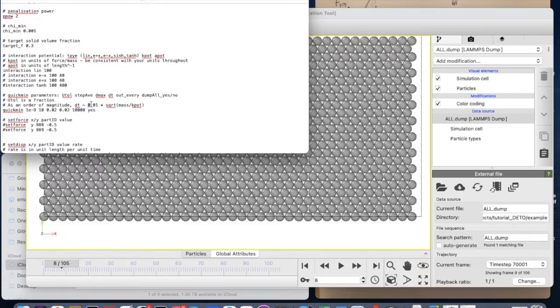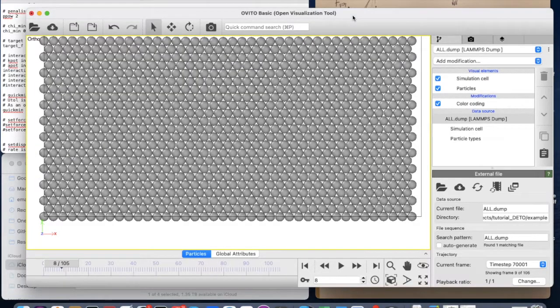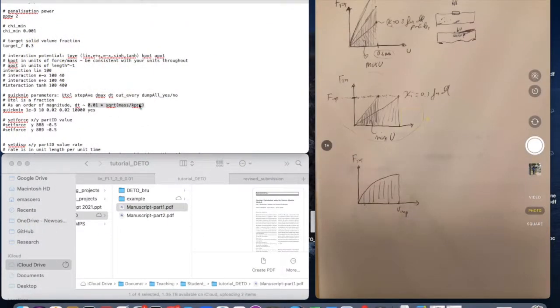It's just an indicative quantity. My suggestion is you take this as an initial guess, and you see whether the system is converging properly or not. If it is not, you make the step smaller. If you see that there are some problems, that it's behaving erratically, you change this value.